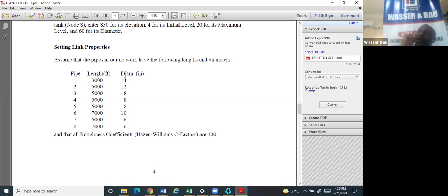Your transmission pipe is usually huge, because it's the one that will transmit water from your reservoir to the upper tank. You don't need it to transmit this water all day. You have to transmit this water within 1 or 2 hours, so the pipe size will be big. If the pipe size you're using in your network is 3 inches, then the pipe going to your overhead tank should be like 5 or 6 inches, and then the pump should be commensurable.